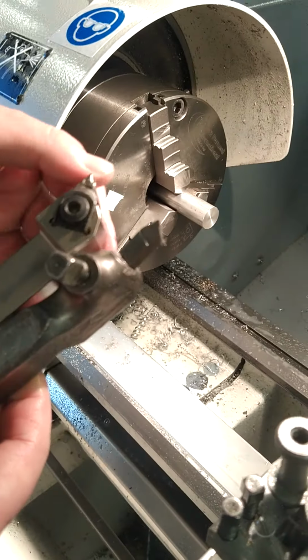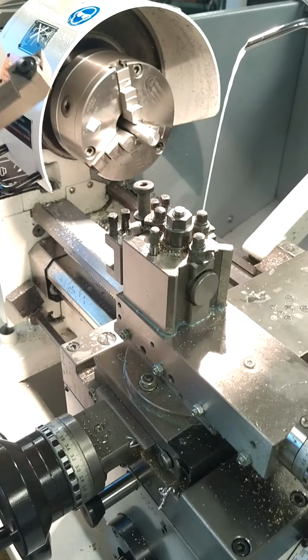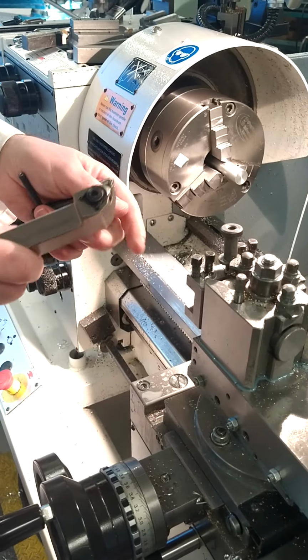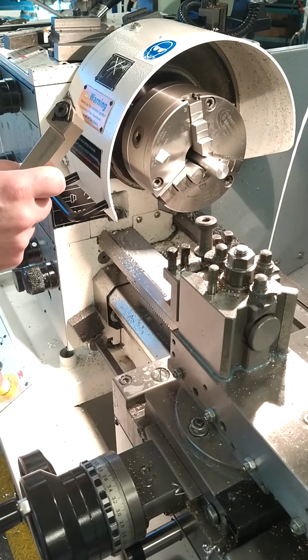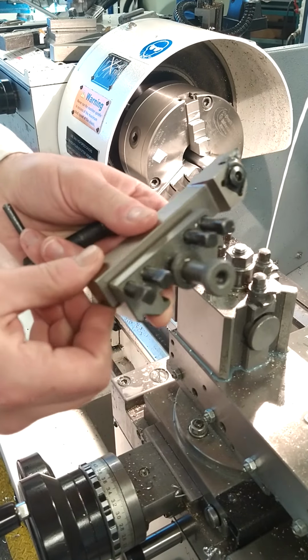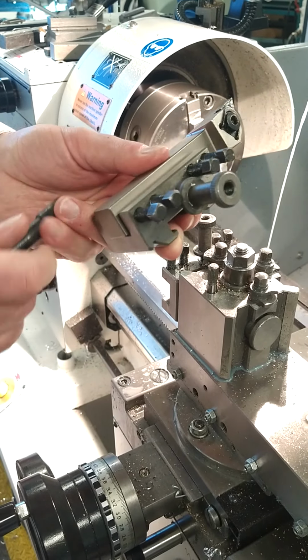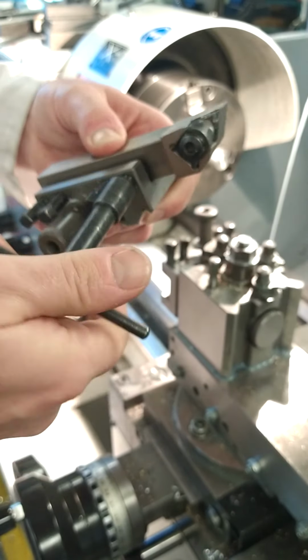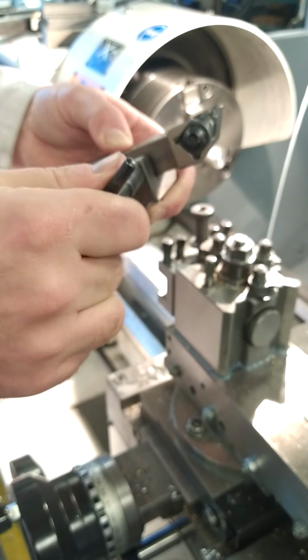So I'm going to install the tool for the first time, and to do that, we're going to need to get the tool holder. So these are the tool holders. They come 3 in a set. We have one currently on the machine. The tool fits into the holder, and then you take your key, and you tighten down those 4 bolts securely.